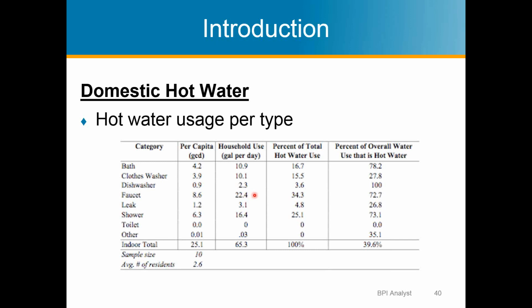Typically 2.5 gallons per minute is the maximum allowable in the state of California, but a lot of commercial restrooms in particular have 0.5 gallons per minute faucets. For $3 you can buy an aerator, screw it on a normal faucet, and cut your hot water use dramatically.